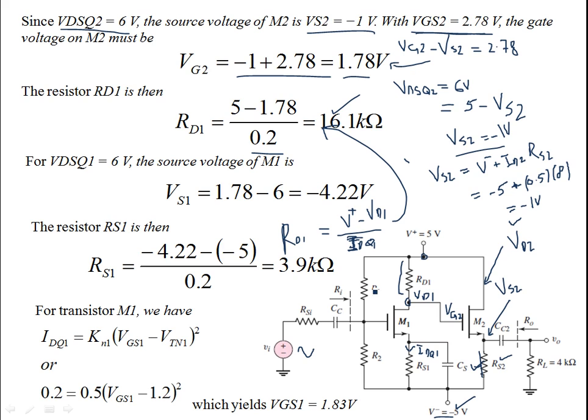In order to put up the circuit, you first need to find these resistances, connect the circuit, and then you have the linear amplification. You can apply a certain AC signal, and in the output it will be a larger value of the same frequency, with a larger amplitude. Linear amplification.